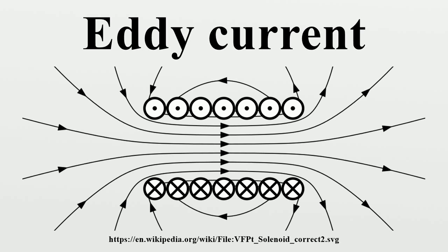An example application is separation of aluminum cans from other metals in an eddy current separator. Ferrous metals cling to the magnet, and aluminum is forced away from the magnet. This can separate a waste stream into ferrous and non-ferrous scrap metal.